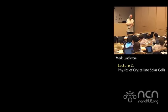There's a lot of interest these days in whether you can find other options, because, first of all, indium is rare, so that's kind of expensive. So you'd like to find other ways to make transparent conductors. There's a lot of interest right now in graphene, because graphene has very high electrical conductance, and a single layer of graphene has very low optical absorption.